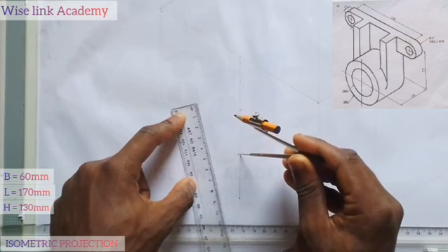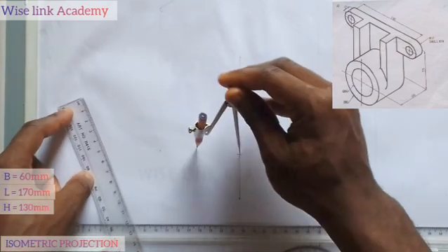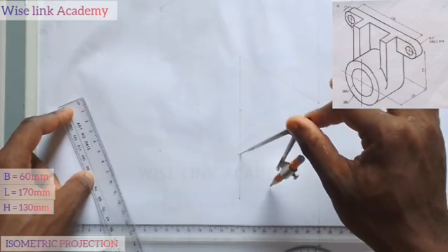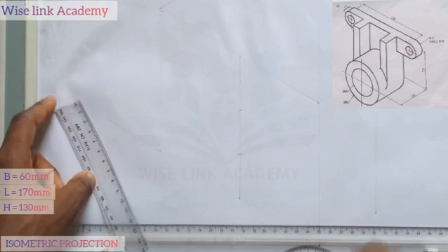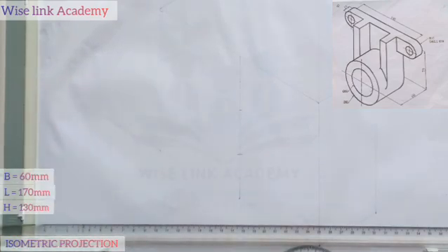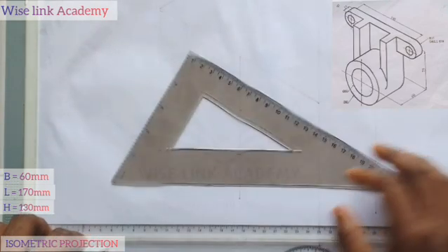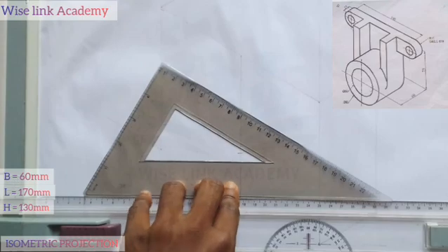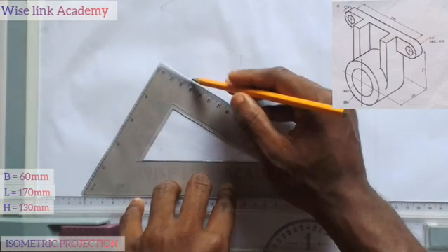Right? So I will now take my set square this way. I'll strike an arc here, faint one. Also strike another arc here, faint one. So I have this. The reason why I did this, you will get to know much better now. Take my set square this way on my t-square. This point here, I will draw down this way with a faint line.